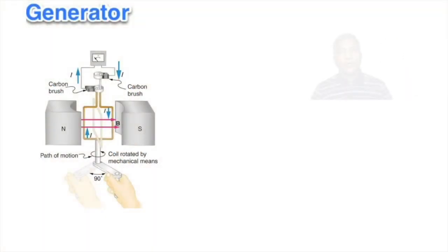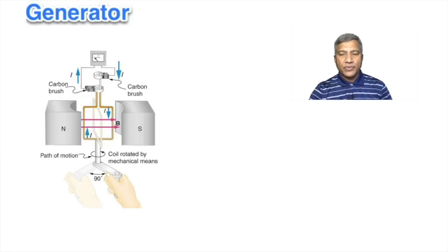Now, we already looked at the principle of the electric generator, where you simply have a coil rotating in a magnetic field. To allow for rotation, you have carbon brushes that are brushing against what are called slip rings. So you have brass rings where you have the copper brushing against it so that there is provision for it to turn without messing up the cables.